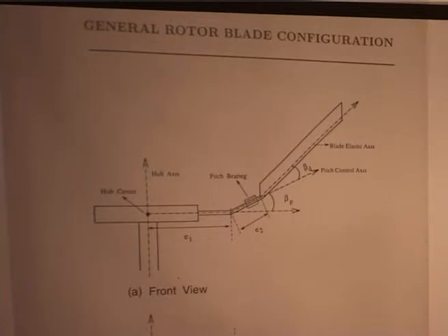and this will have a lot of effect in torsion. So, you see flap, if you look at it, in both configurations there will not be a major change. Lead lag there will be a change, torsion there will be a lot more change, which will go to pitch link load. Then you say which one is better. Okay. This debate goes on because changing a configuration from one to the other is not an easy task in the actual design. Finally, you live with it, whatever load that comes, and you try to minimize something here and there. So, each has its own plus and minus.